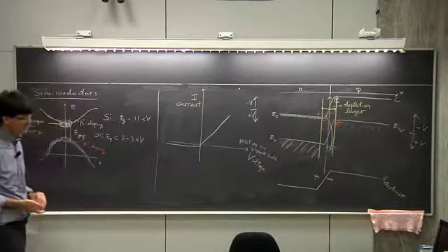What's the scale of the devices at which we have the same physics that we see? I would say of the order of microns, a few microns. For example, your system needs to have a depletion layer which is small compared to the size of your system. Otherwise, this will be the entire system. If this is, say, 100 angstroms, your device cannot be smaller than that because otherwise everything becomes a depletion layer, so it's meaningless. So I would say that down to the size of, say, 10 microns, this kind of physics is still dominating. Below that, it's a different story, clearly.